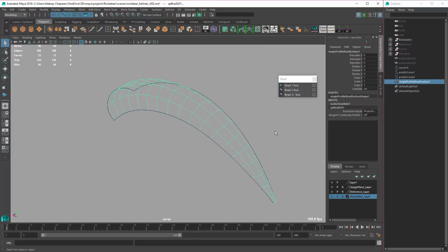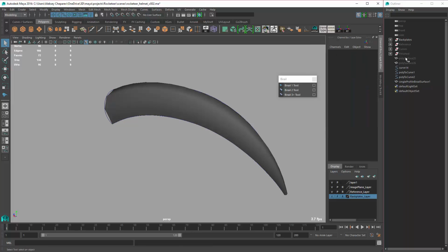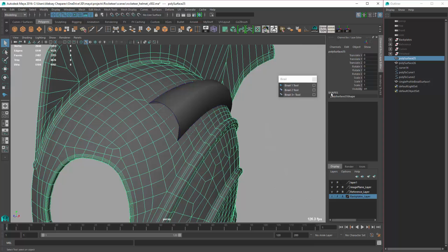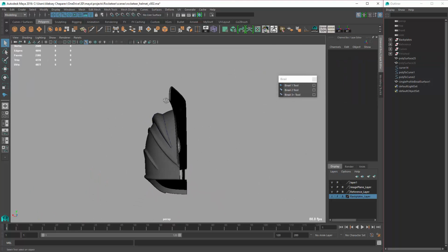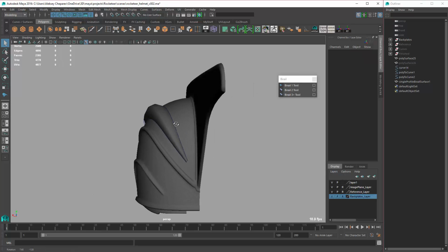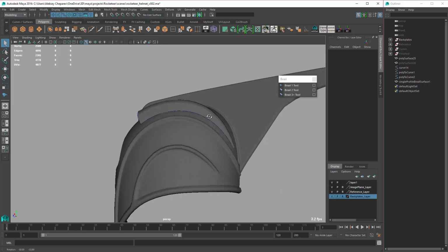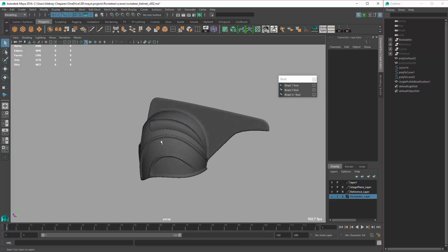It's going to say select the profile curve there, and then it says select 2 rail curves, 1 and 2. There it is. Let's just reverse it. Alright, so let's take a look. Let's see if this is working. Actually, I think that looks pretty perfect.